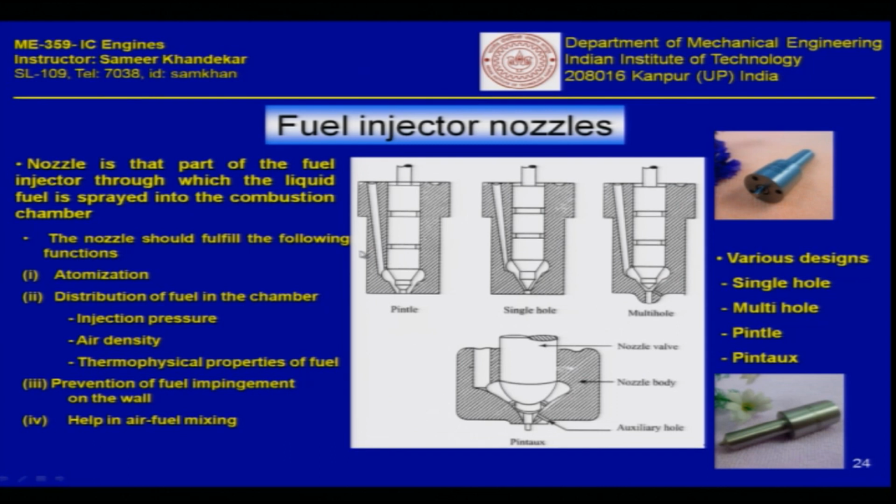So, here are, let us say, some types of nozzle designs which are available. You can have a single hole, for example, you can have a multi hole, you can also have a pintle nozzle, which is a single nozzle like that, or a pintaux nozzle, which is here. Now, it depends on the way this pin is sitting on this spray. So, in a single hole there is only one hole. In a multi hole there are several holes, and you can see a photograph also on the right hand side. You can see the photograph from the other side here.